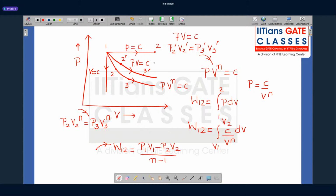Also, if you try to plot the area, because what is work transfer? Work transfer is basically the area under the curve. Which curve? The area under the process path. Between 2 to 3 and 3 to 4, for different process paths, the areas are different. If I go with one path and then with this other path, the areas under the curves are different. So what is this indicating about the work transfer mechanism? Let's understand this with a different diagram.